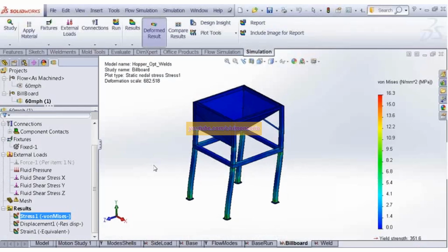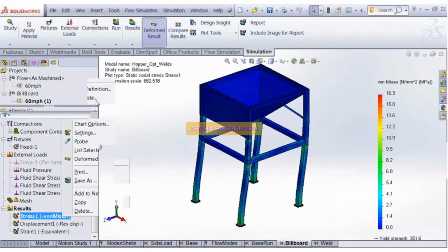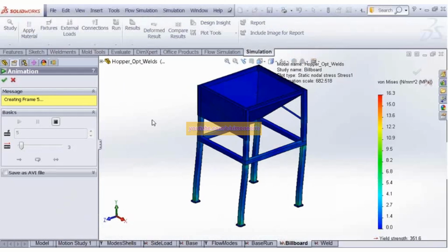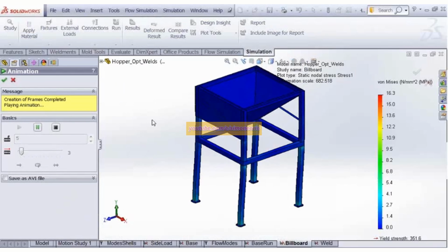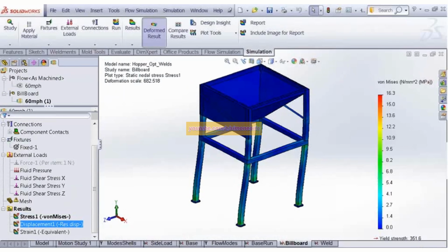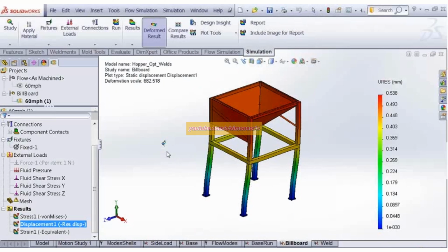And the stress results are not too terribly different, a little bit worse because we put a big plate on the model. So 16 versus 15 megapascals, but still a pretty high factor of safety. And then our deflections were slightly increased. And then we can extend this simulation from here and start playing what-if scenarios.